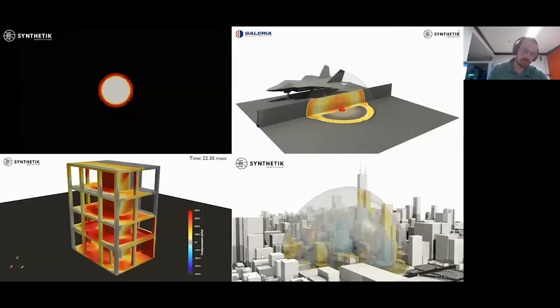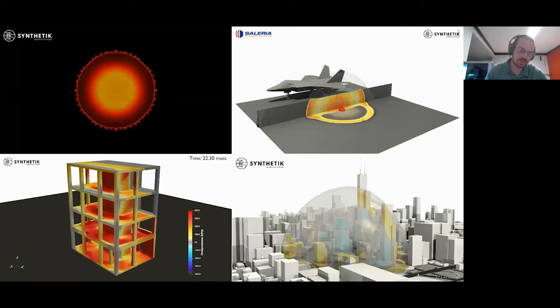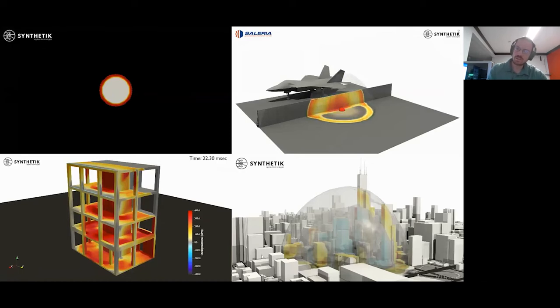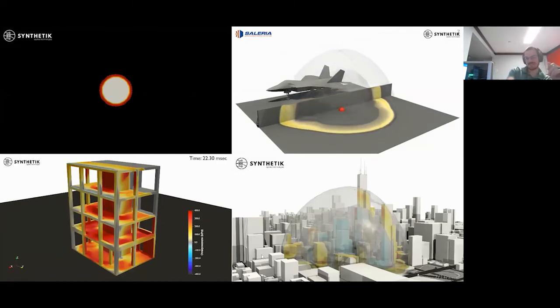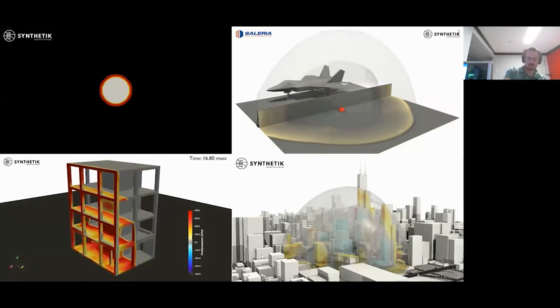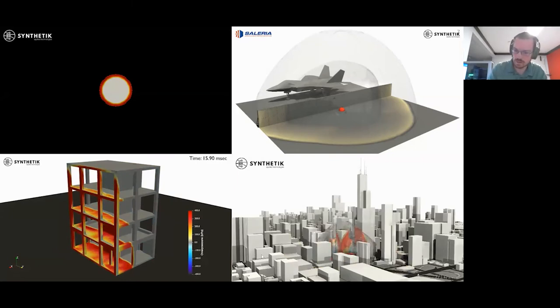And then here are just quick video examples. So there's the Taylor-Rayleigh instabilities where you can see the density gradients. We have more complex geometries. Next, we did some work. This was a very large case. I think it was 12 tons detonated in a field. Basically, they were looking at the structural response of this structure in particular due to the loads. So we ran these calculations and we sent them to another team who actually did the structural response using the loads. And then this is a typical cityscape detonation that we use to estimate damage, that kind of stuff.